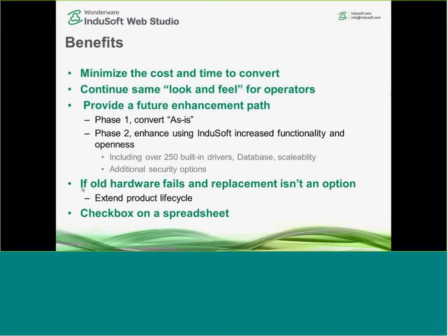Another benefit is if you've got an older hardware line, proprietary hardware, and it fails, and replacement just isn't an option. It's not available, or you can't find it online, or it's got to be shipped from far away or built. Maybe lead times are very, very long. So this allows you to extend your machine or your product life cycle by being able to convert your applications from another product into InduSoft Web Studio.